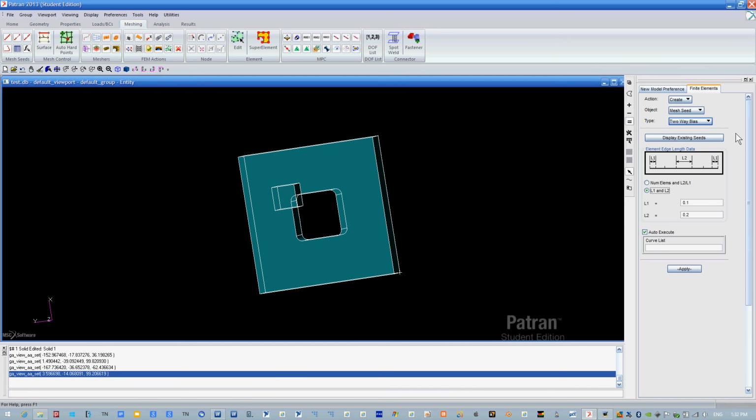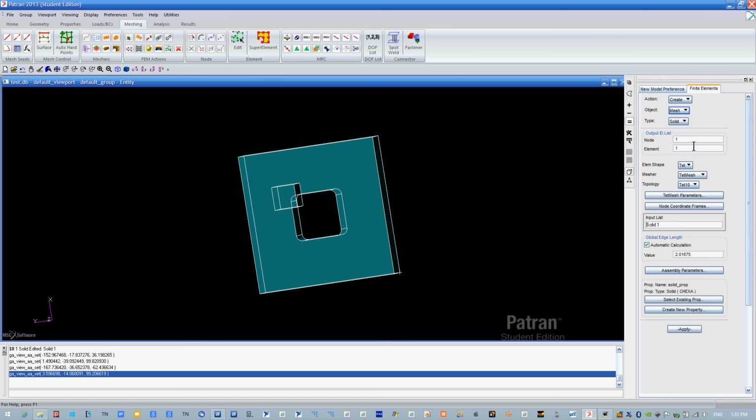Assuming linear elements, what is the minimum number of elements through the thickness of the part that you need? So that depends on what you're trying to get. I know you can model a lot of the three-dimensional stuff in 2D, but if you want to do a 3D analysis, you can select different mesh types. In this case, we're doing tetrahedrals, and when they're constructed through this, in some sections it goes all the way through once. This is not a very big model, but it really depends.